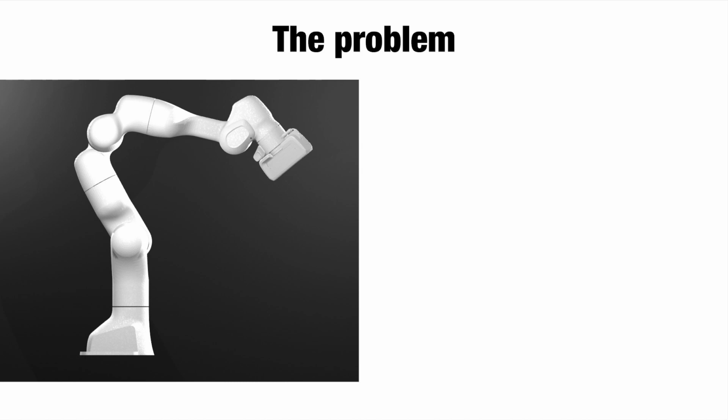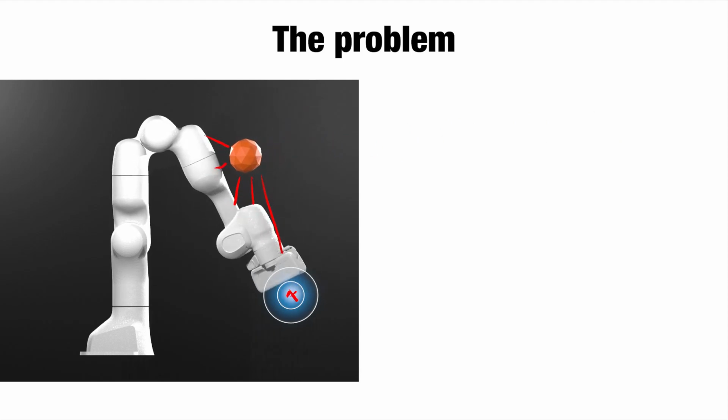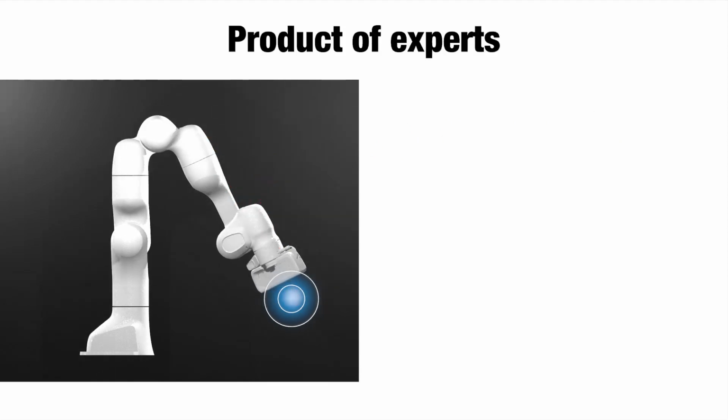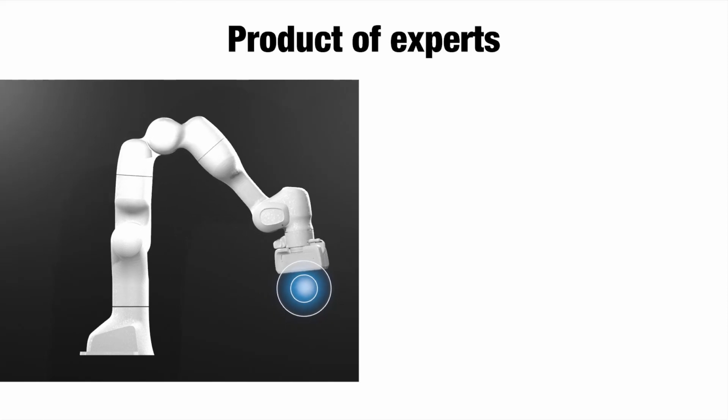Often, it is easier and more elegant to define the distribution under several task spaces. For example, a Gaussian distribution can indicate preferred position of the end effector. Obstacle avoidance can be defined as a distribution over distances from objects. In this work, we propose to use the product of experts as a framework to fuse together these different distributions as a distribution over robot configurations.